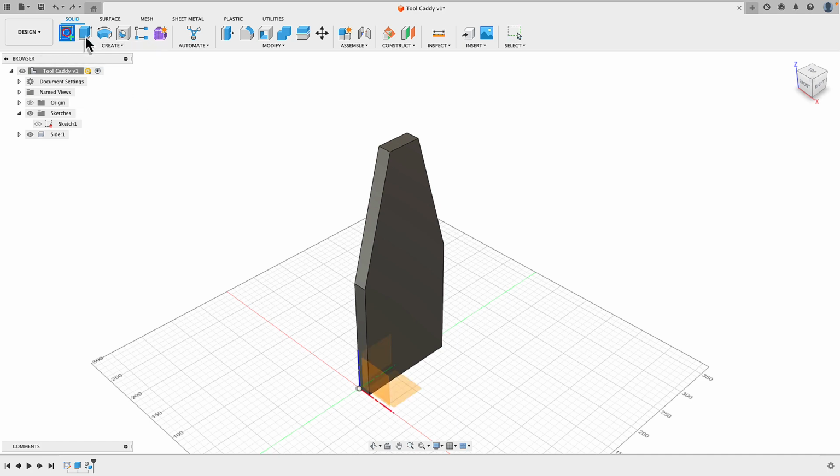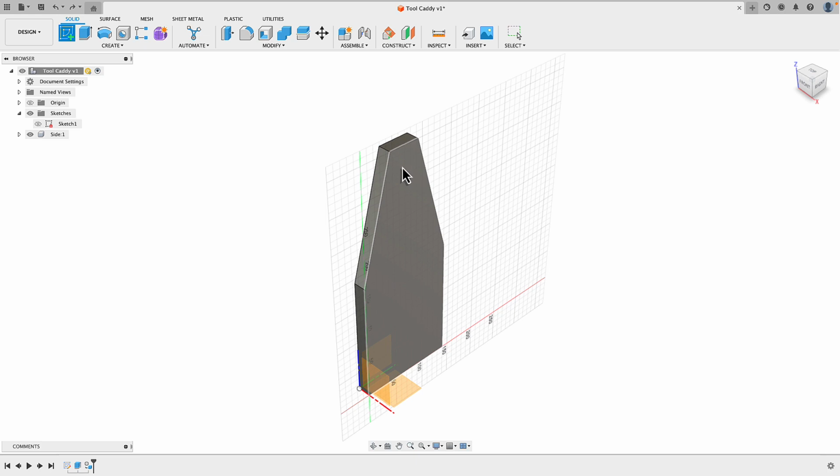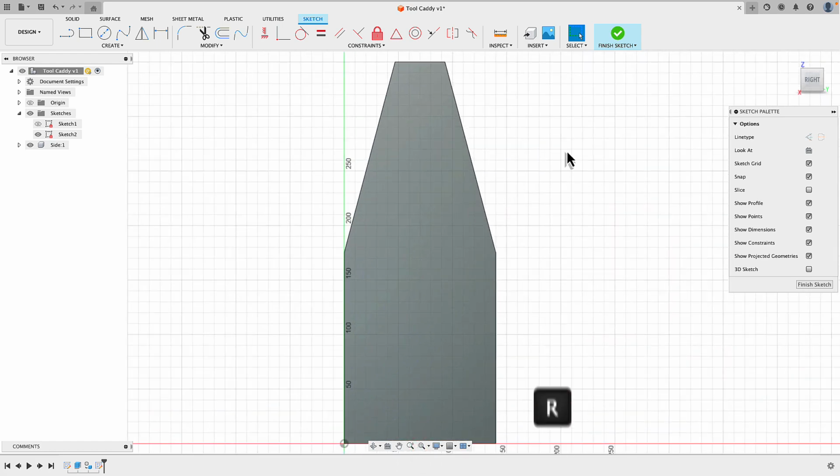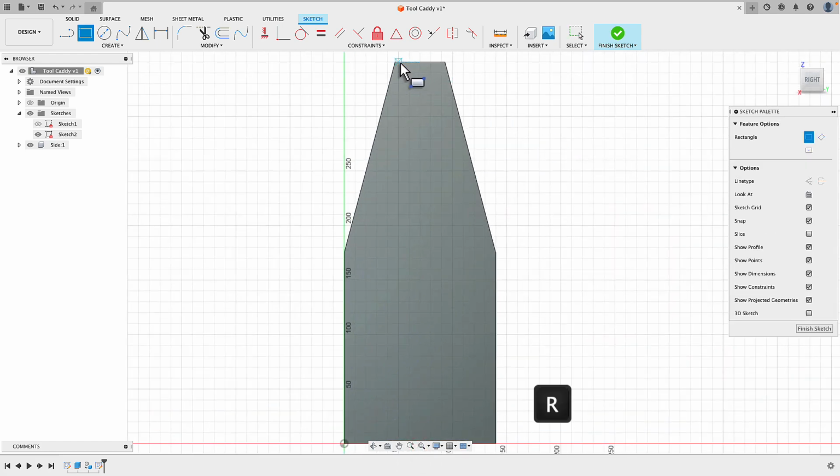So we've got a new sketch and we're actually going to sketch off the inside face of the side here. So we need a rectangle and it needs to sort of join up to the top line here. It kind of doesn't matter exactly where you start from, just as long as it's joining up to the top of the side. And in terms of dimensions, it's going to be 19 millimeters thick, which is a standard timber dimension, tab, and it's going to be 68 millimeters wide.